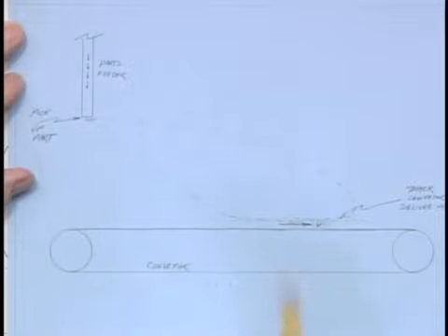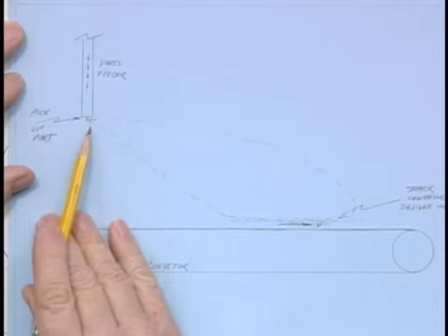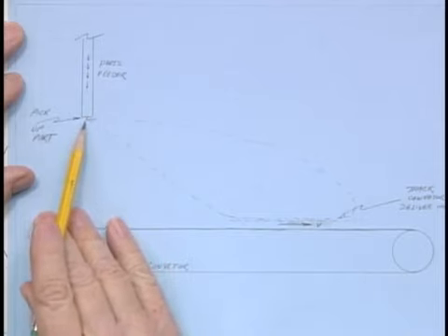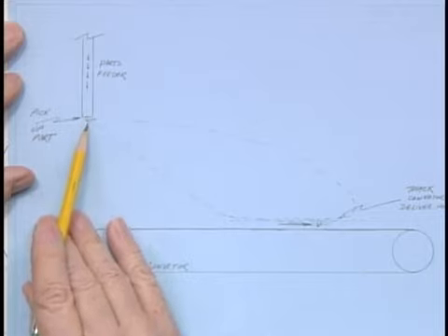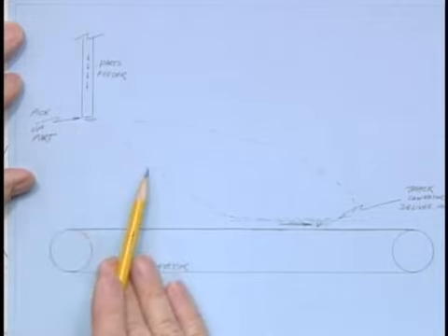So my concept that I start with is to say, well, gee, this is a nice application for a cusp because, look, this parts feeder is stationary. It's on the ground plane. So if I'm going to pick something off the bottom of that stack, I've got to be stopped, at least for an instant. And a cusp is exactly that. It stops for an instant. So if I stop just long enough for a vacuum or some other means to suck that part away, I then want to accelerate the part down some path.